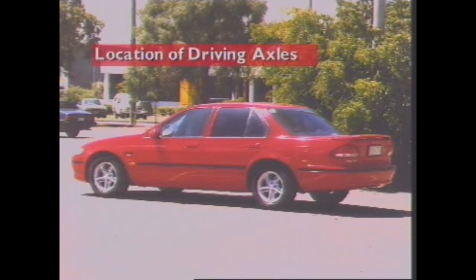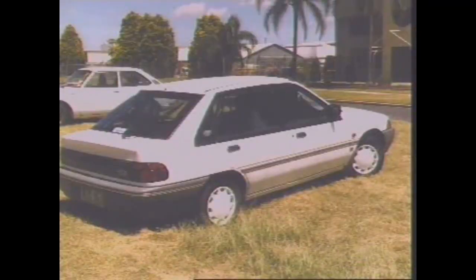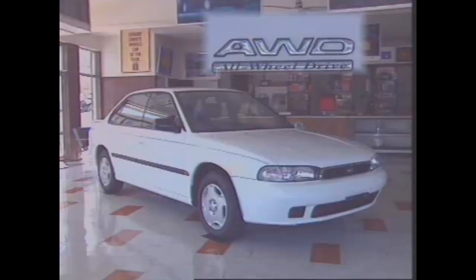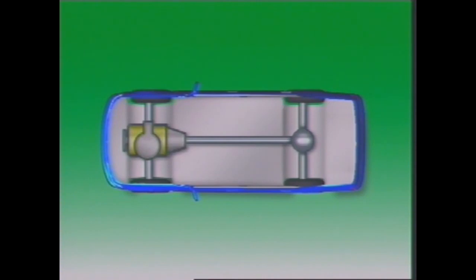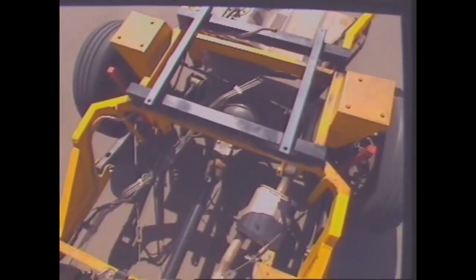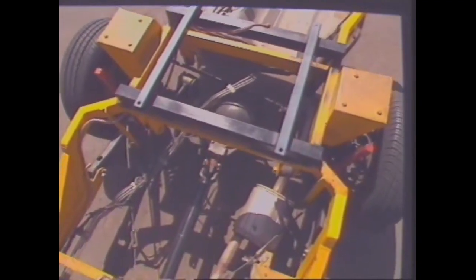The location of the driving axle determines whether the vehicle is classified as rear-wheel drive, front-wheel drive, 4-wheel drive, or all-wheel drive. Rear-wheel drive vehicles can use a conventional layout with the engine at the front of the vehicle. The torque from the engine is transmitted to the rear-mounted driving axle by propeller, or drive shaft. This spreads the weight of components throughout the vehicle.